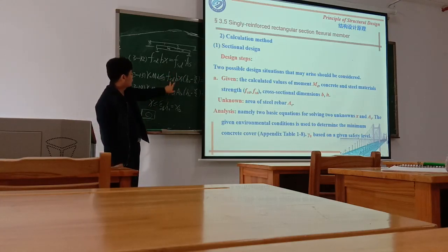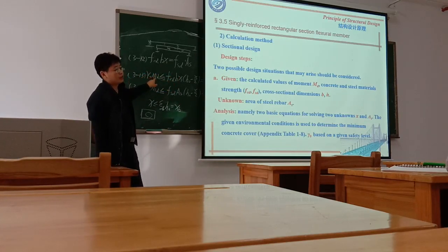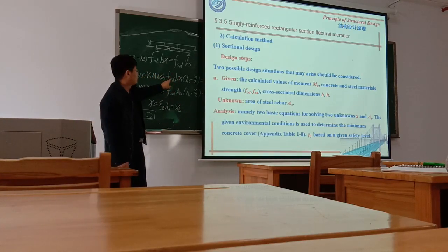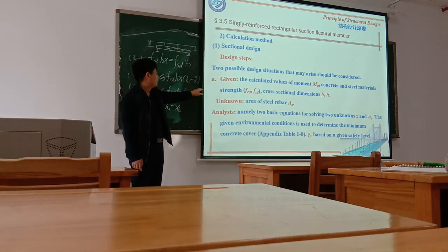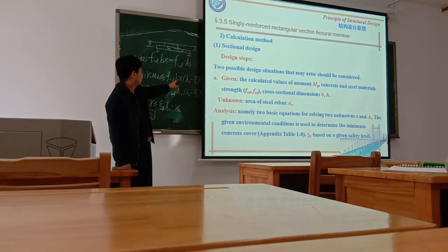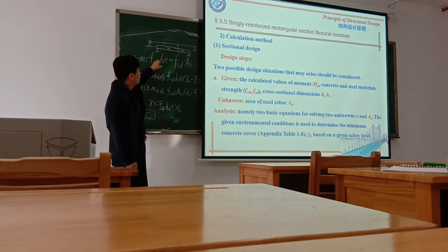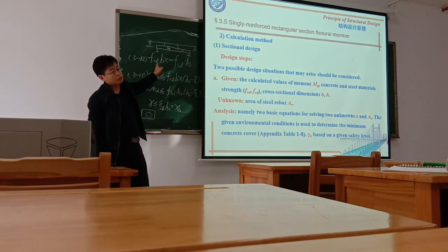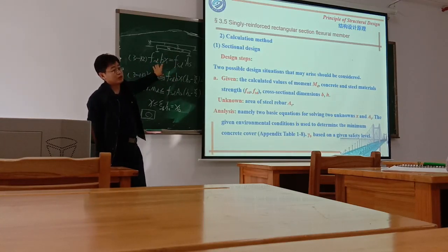And in this formula, this part, Md is given to you. In this side, in these two formulas, x you don't know and As you don't know. Two things you don't know, but you have these two formulas. So it's easy to just solve this.